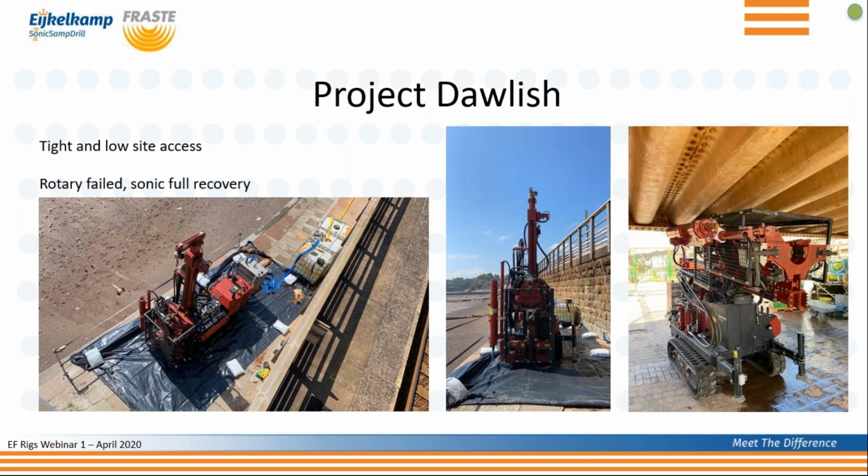So basically, if I was on there with a CP rig, which is what I've spent the last 5 years on, it'd take me a very long time just to get through the brand new material. And you'd have to start in 10-inch, 8-inch, and 6-inch to get to the required depth of 20 metres. The reason I say 10 inches is you'd have to smash all that stuff above. It would probably take you over a week to smash through it.